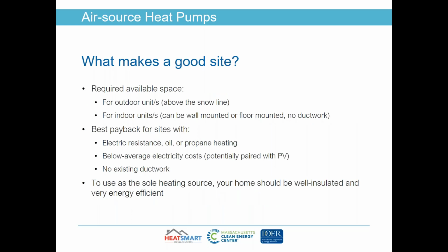What makes for a good site? First of all, they really require very little space. You just need a few feet for the outdoor units, which need to be mounted above the snow line. And then the indoor units, you saw the pictures there, they can be wall mounted or floor mounted. And again, you don't need any ductwork. You see the best paybacks for sites, first of all, that are using high cost heating fuels, so especially electric resistance, but also oil or propane. And then if you have below average electricity costs, particularly if they're paired with solar PV, then you're really going to minimize the cost of operating the heat pump.